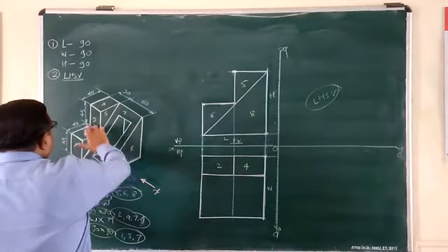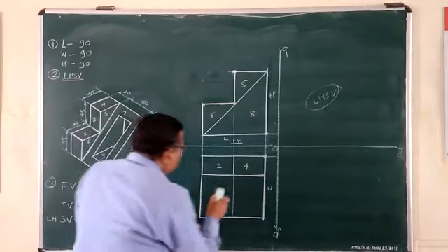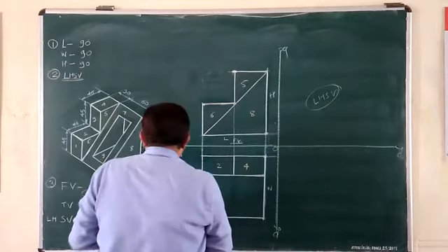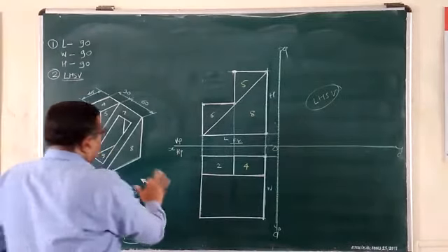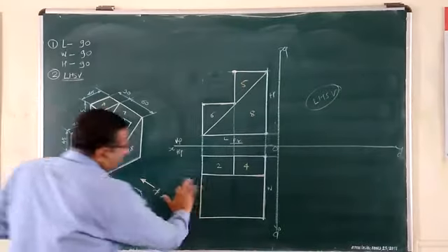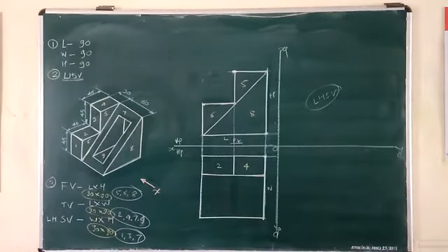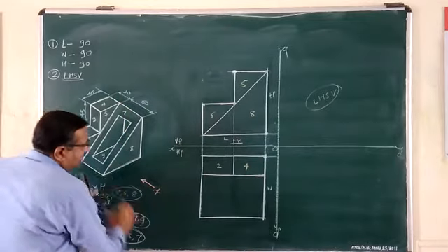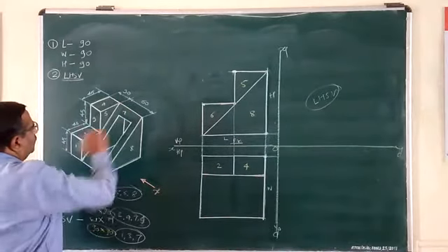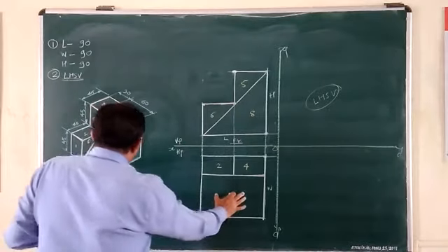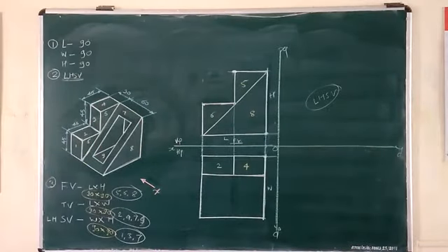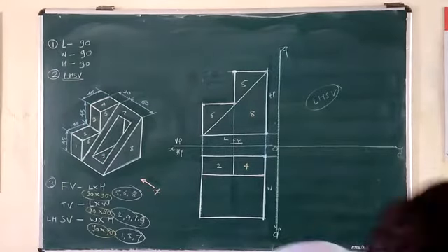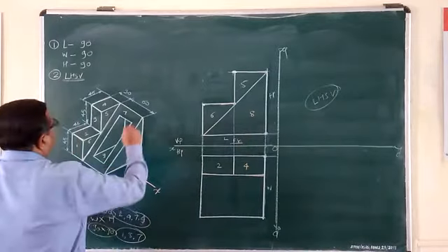Now, no more line creation on this surface, so I will just erase this. Whether this is slant? Yes, slant. Though it is slant, in top view it appears as horizontal, with compressed length. This is the true length. What we are getting is its apparent length. That is here. Okay. Now this hole will appear on this surface. The dimensions of that hole I haven't mentioned here. Just I will show it here.